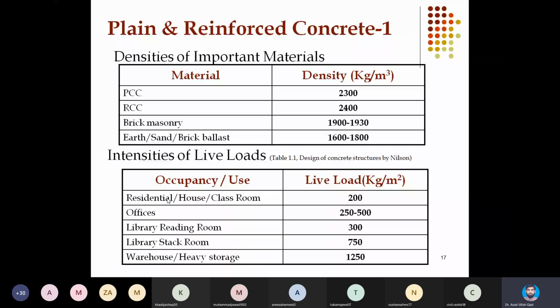If the answer comes out to be yes, then the permission can be granted. But if the change in the structural use will make the loads bigger and factor of safety is compromised, then obviously the permission will not be granted, or otherwise strengthening of the structure may be proposed.